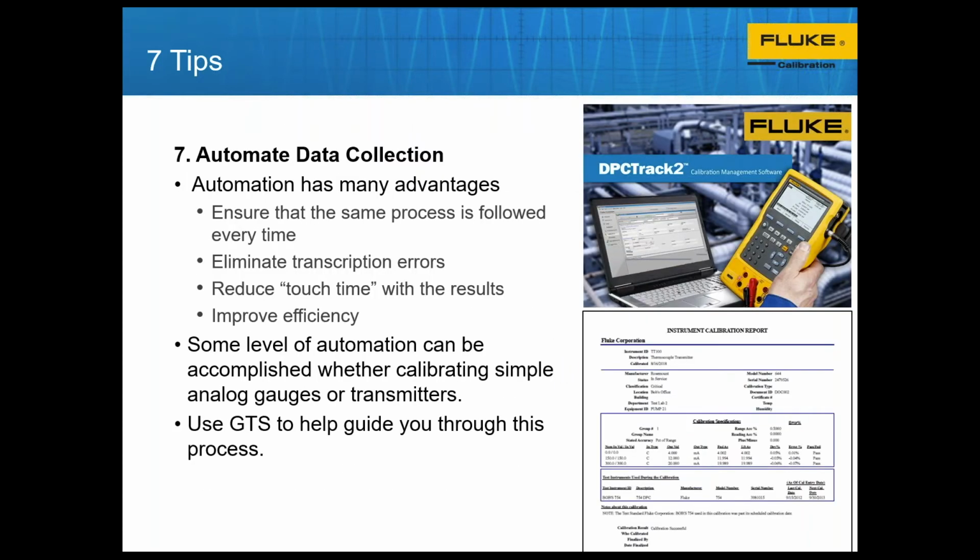Finally, when you have the opportunity, try to document your calibrations. This isn't just a comment because we have documenting equipment and we want you to buy them. From a user point of view, if I'm walking out and I'm doing a calibration, I may have a pump, a pressure source, like a standard that I'm measuring. I may have tubing, wrenches, fittings, tape. I'll have an electrical device that's going to provide potentially 4 to 20 milliamps and make a connection on that side and make some measurements for me. Maybe a multimeter to do some switch testing. I may even have to take a communicator in the field.